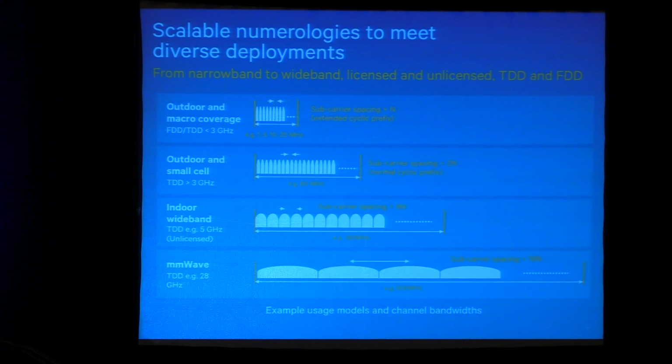If you compare today's 4G LTE with the Wi-Fi family in that band, the way to achieve the very wide bandwidth with today's 4G LTE is through carrier aggregation. And if you make a receiver that's wide using that method, it works just fine. The performance is very good, but there's an extra cost delta for that. So by defining these flexible spacings and being able to drop down 160 at once, or even wider for the mmWave, we can produce efficient designs that are very cost competitive, all the way up to 28 gigahertz, actually 60 gigahertz, maybe 72 gigahertz, and that's what we're trying to do.